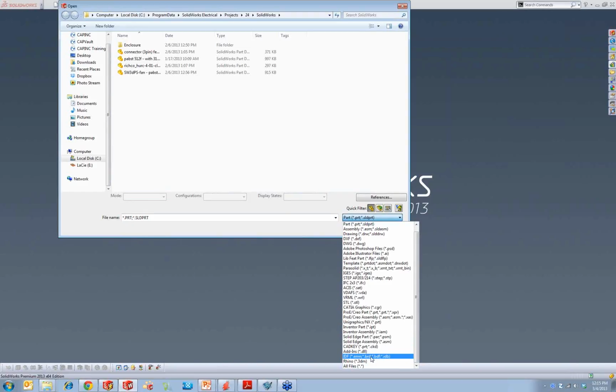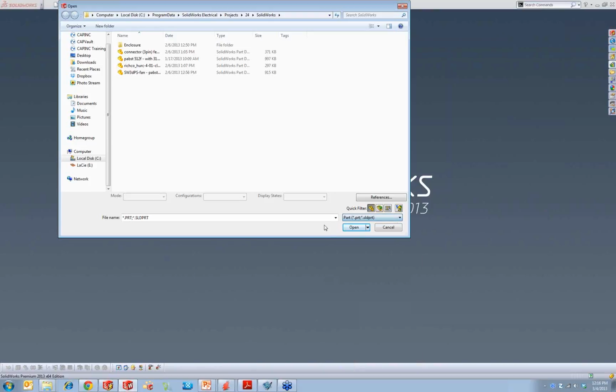Lite, which actually comes with every seat of SolidWorks, and it will bring in a circuit board file of a certain type. There are 3 different levels of IDF: 2, 3, and 4. This will bring in IDF level 2, which is really just the board layout, the component placement, and the keep in and keep out areas, but nothing beyond that. And it also creates it as one big solid file, so it's going to be a big file. It'll perform poorly if it's a large circuit board.